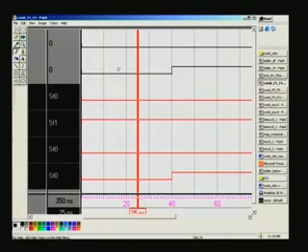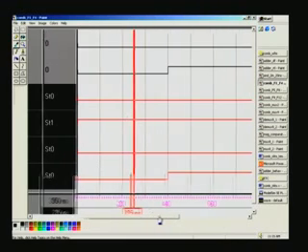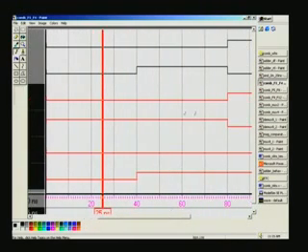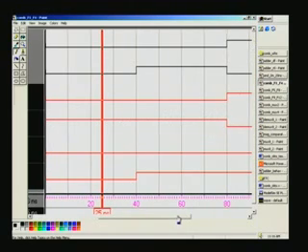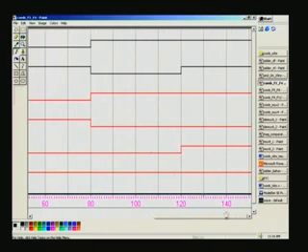See, this is 0 here, this is 0. And now what we are looking for is the second output, which is the inversion of A. So what is happening here? You can recognize that this is high here because the input is low here; this is the inversion of that signal. So it is high here, that's what you want. And when the input goes high, it goes low, because it is an inverter. So you have thus checked the functionality of the inverter as such.